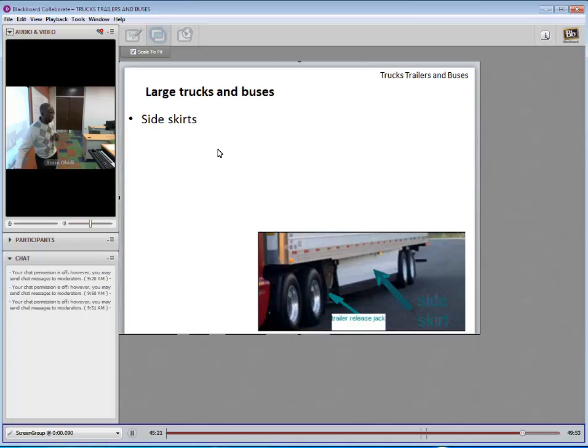The whole idea is that for a greater downforce, you want a wider gap in the front than in the back. But the exact opposite is what's common in design. The side skirts are either straight on both sides or they are wider as you go to the back. Certainly, it's not an aerodynamic reason that causes that design. It's probably a logistic reason.